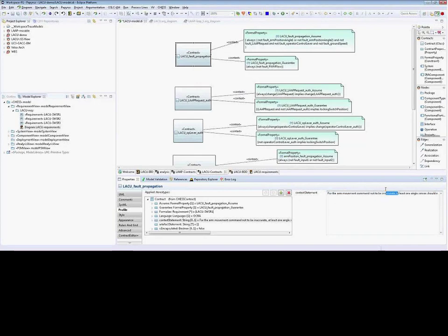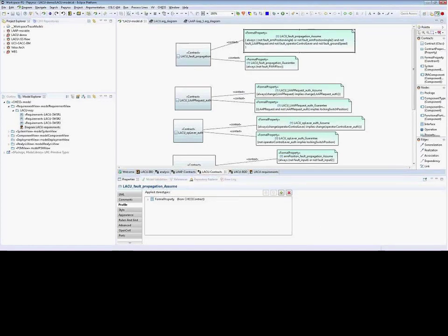So, for example, for the arm movement command to be accurate, at least one angle sensor should not be faulty, and we have here two angle sensors used in the system, as well as the ground speed sensor. Moreover, the user inputs and control level should be assured also.